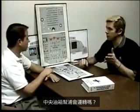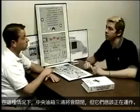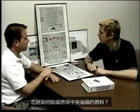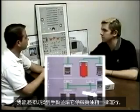Would the center tank pumps be operating? The center tank pumps would be off in that case, and they should be operating. So the auto feature has failed. How would you continue to burn that center tank fuel? I'd select the switch to manual and allow it to run just like the wing tanks.